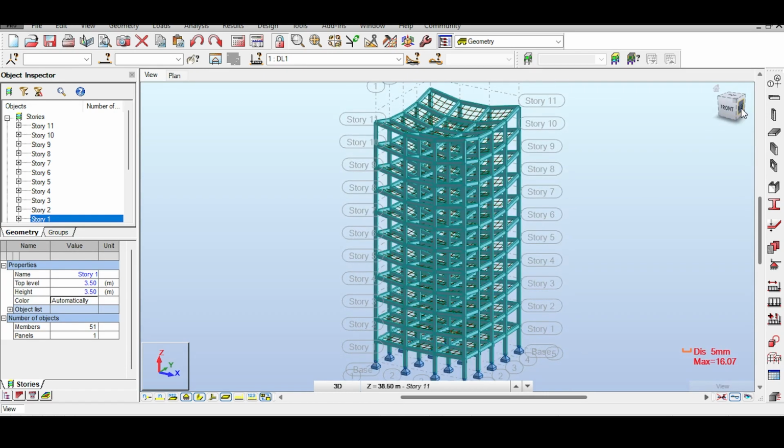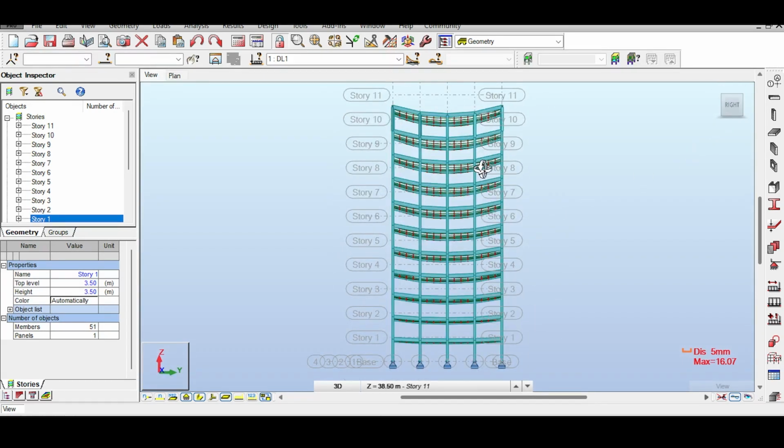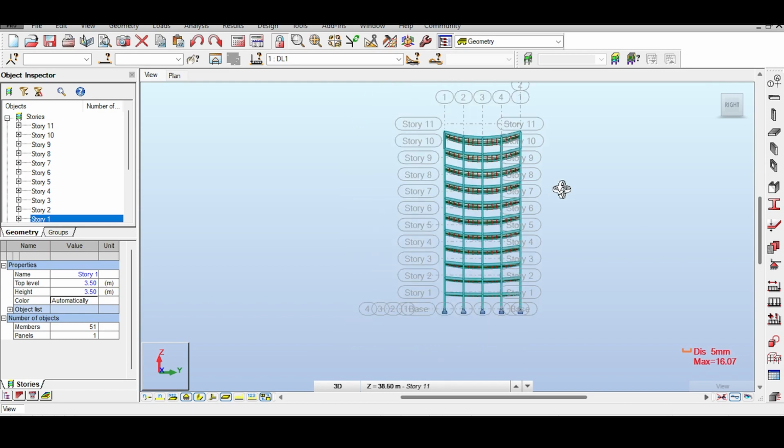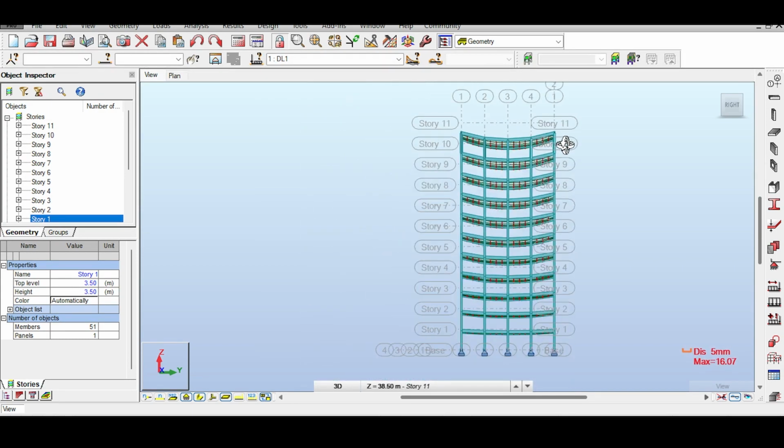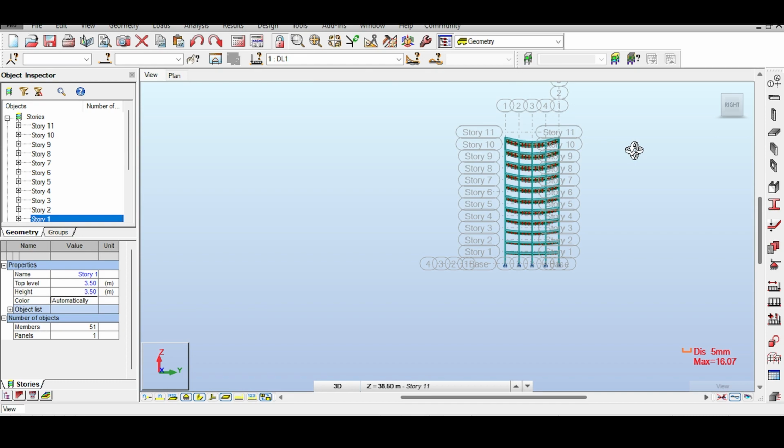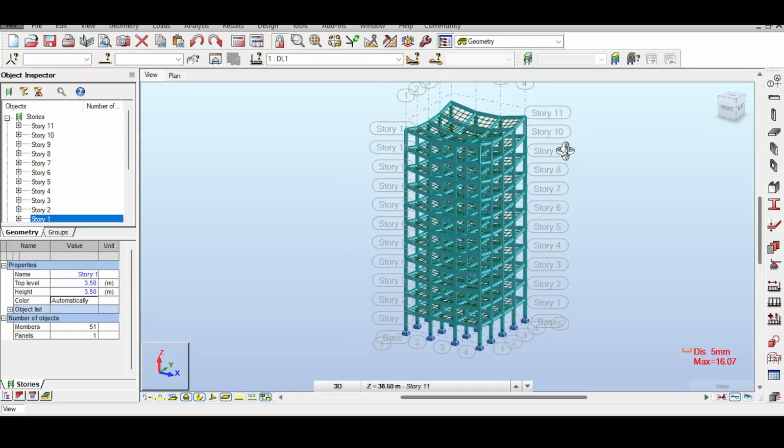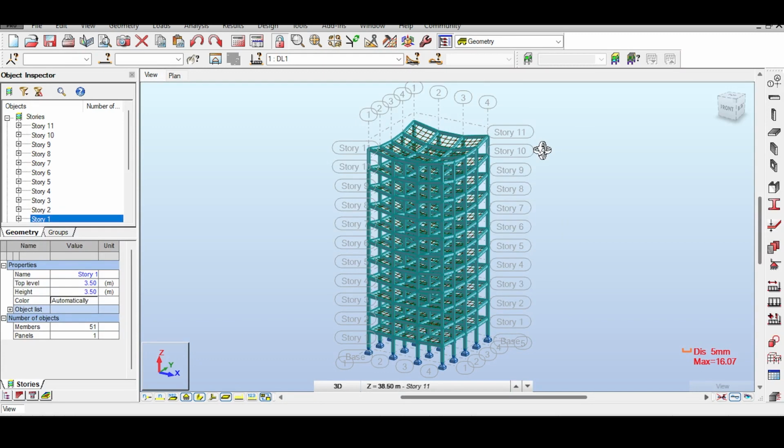What about the left or right side? Same thing. It's perfectly vertical. There are some sideways motion, but there is no generalistic sideways swing. So this is what you would expect. Like if somebody tells you, hey, I have a structure with gravity loads, you would think, okay, deflections are vertical, and there is no significant deflections horizontal because there are no horizontal forces applied.